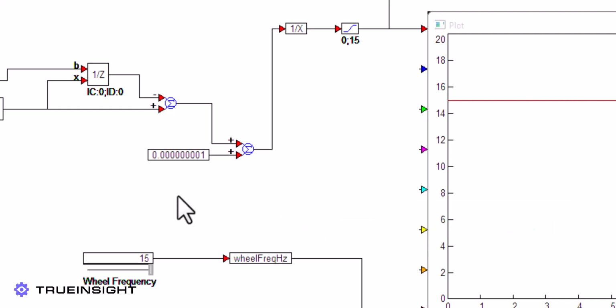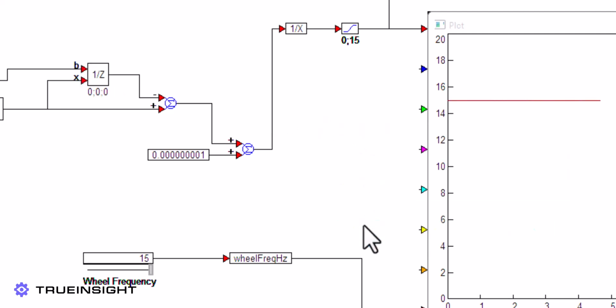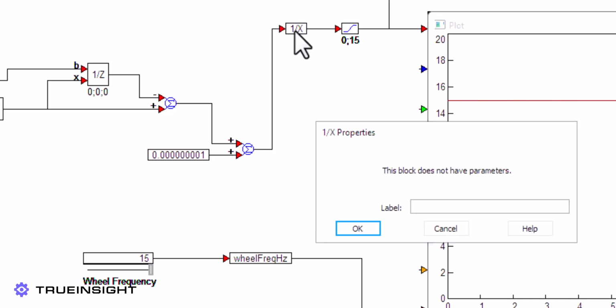Next, we will use the trigger again and the output of the sample and hold as inputs to the unit delay block. This will allow us to preserve the real-world time value from the pulse immediately preceding the current pulse from the trigger. With these pieces of information, we now have the time values for 2 consecutive pulses, and taking the difference between them will provide us with the time between them, which is equal to the period of our